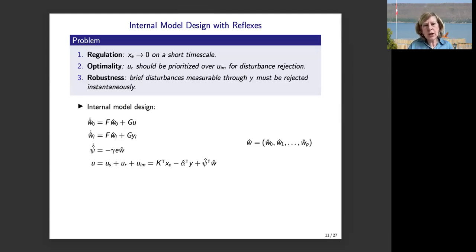So what we do is we take an internal model design that's basically a little bit souped up from the previous design. So we have the previous design that gave an estimate of the signal D. We then do some filtering on our sensory measurements because sensory measurements are noisy and we don't want impulsive disturbances to come in through anything on the internal model side. So we filter sensory measurements so impulsive disturbances don't go there. And then we have our standard gradient law, but with an extended regressor with this added filtering. So it's a bumped up internal model, a little bit redundant, in fact.